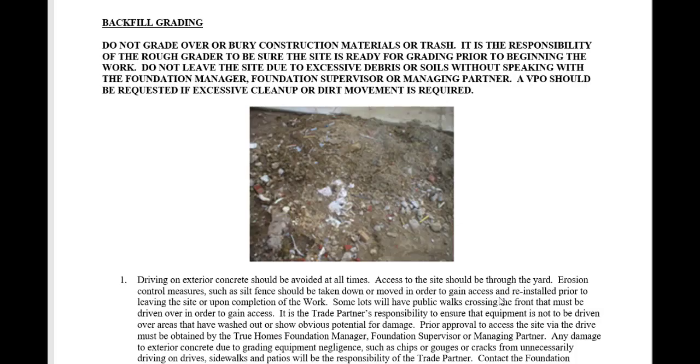Moving on down into backfill grading. Do not grade over or bury construction materials or trash. It's the responsibility of the rough grader to be sure the site is ready for grading prior to beginning the work. Do not leave the site due to excessive debris or soils without speaking with the foundation manager, foundation supervisor, or managing partner, as well as the builder. The VPO should be requested if excessive cleanup or dirt movement is required.